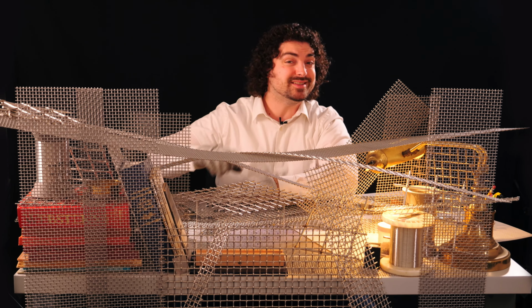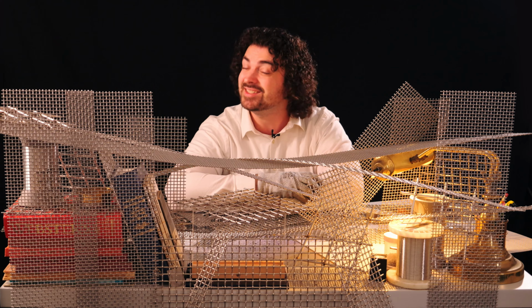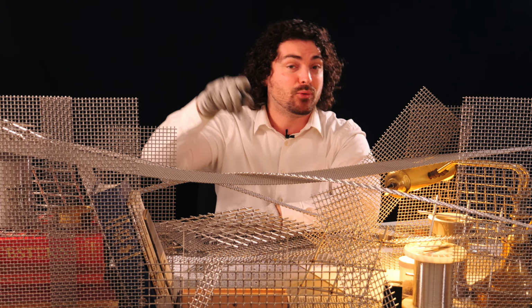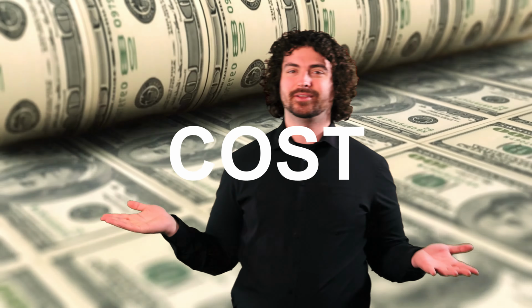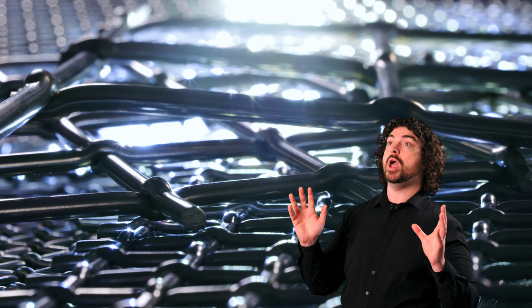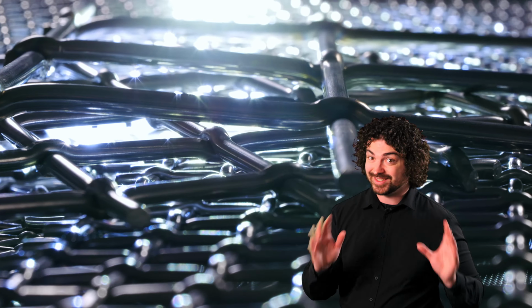But there is a secret second reason why stainless steel is the most common alloy in the world for woven wire mesh, and that reason is it's cheap. And honestly, that's kind of the crux of the whole thing. Yes, there are scenarios where you need Hastelloy, where you need Inconel, but those are specialty alloys that are way more expensive than common stainless steel grades.